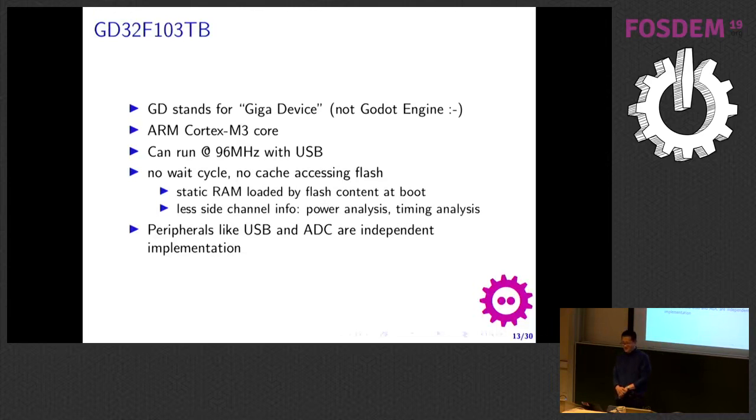Yes, the game engine. But it uses a licensed ARM Cortex-M3 core, but the peripheral is an independent re-implementation of the ST micro. And the good thing is that it has no wait cycle to the flash access. Actually, it is a static RAM based architecture, and the static RAM is loaded by flash content at the boot time. And so the access to SRAM is no wait cycle.